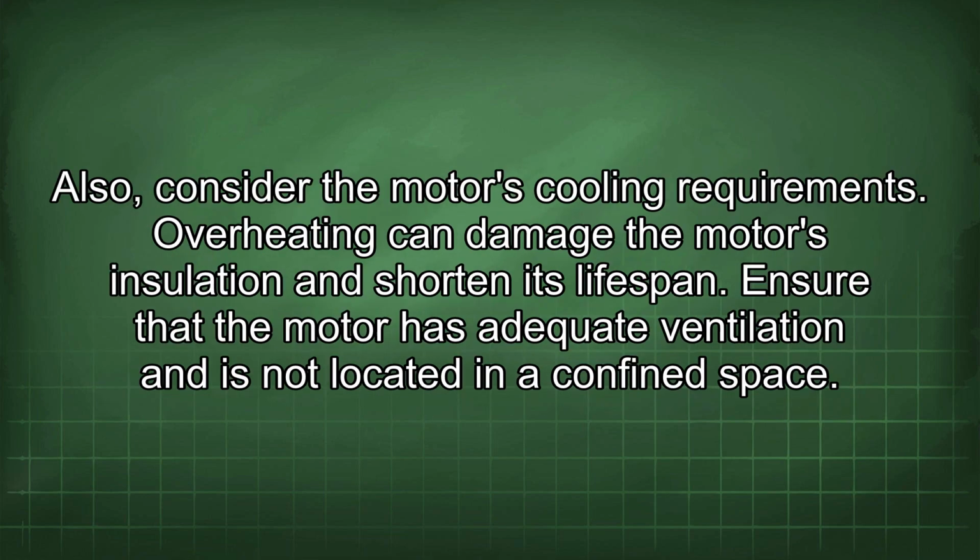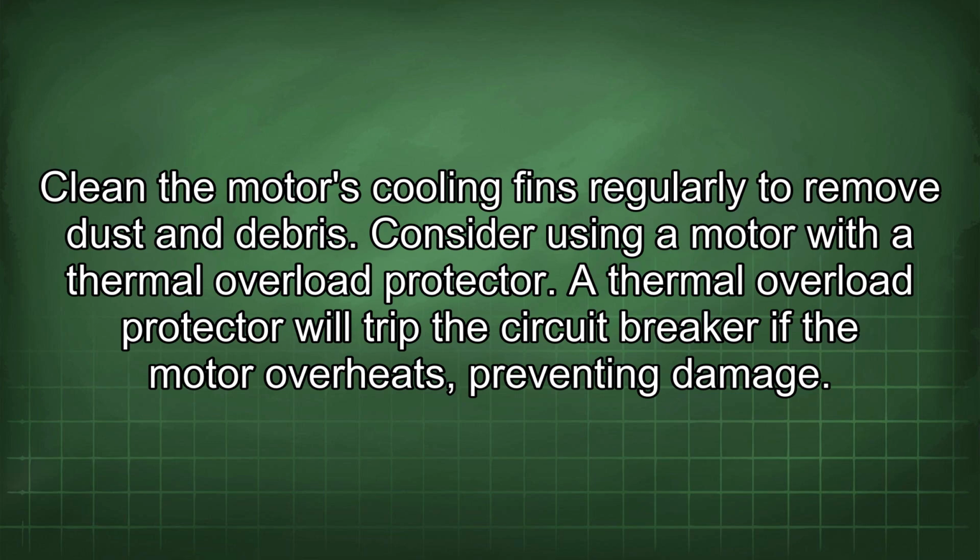Also, consider the motor's cooling requirements. Overheating can damage the motor's insulation and shorten its lifespan. Ensure that the motor has adequate ventilation and is not located in a confined space. Clean the motor's cooling fins regularly to remove dust and debris. Consider using a motor with a thermal overload protector. A thermal overload protector will trip the circuit breaker if the motor overheats, preventing damage.